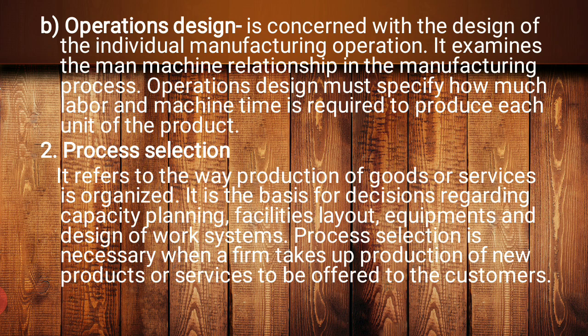Suppose the first stage may require 2 equipments and 4 people and maybe 30 minutes. Then this is what is said to be operation design. Operation number 2 may require 3 machines and 6 people and 1 hour. That means this is the whole designing of that particular operation or stage only, and that is a part of process planning. So process planning has two things in mind.